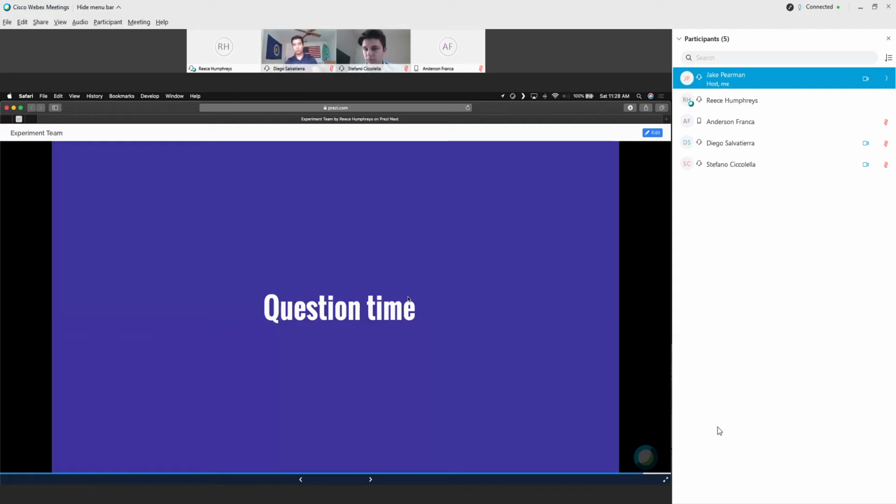Yeah, definitely. In terms of the reaction wheel, since that's a specific example, I'll work with that. The way we want to handle that is to model the physical system and use physics to do all the predictions. If you have the mass of the wheel and you know the RPM of the motor that's going to be spinning it, we can calculate how much torque that would produce on the vehicle or the satellite. So the first step would be to identify the ideal conditions: using this mass and this motor, we should be able to produce this much torque. That's the idealized case.